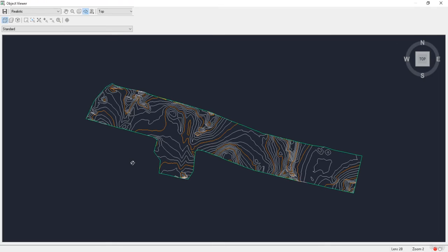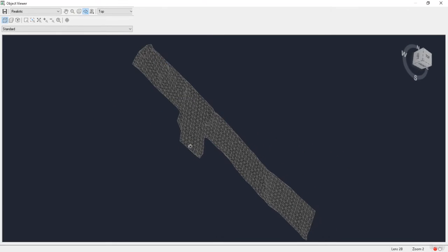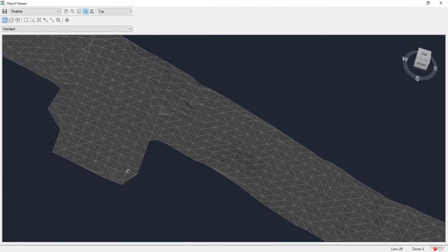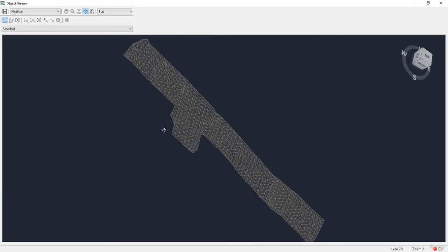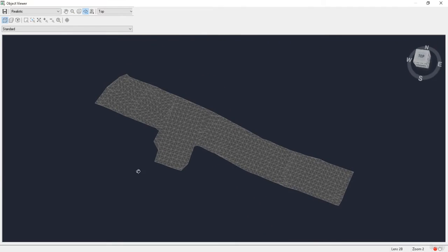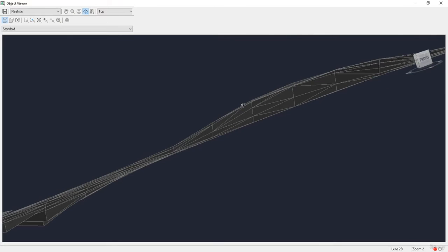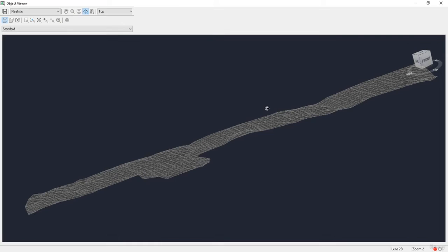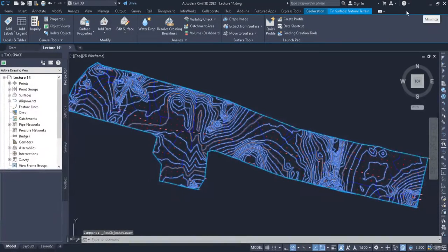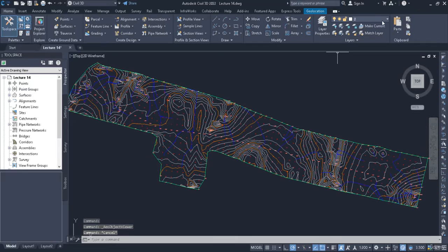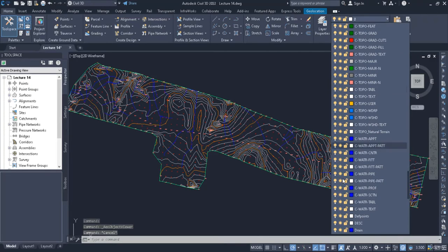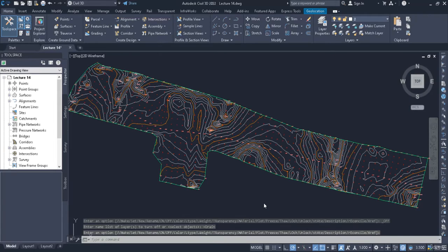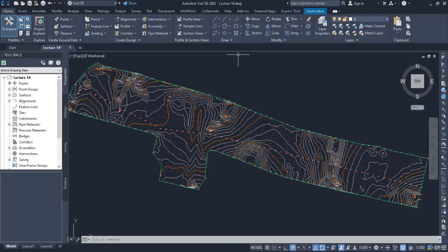We can go to the object viewer. You can see the slope areas. So this is the point where the water is going. See, if we land on these points, it will definitely go to the areas which are at the lower elevation. Let's turn off the drain layer from this point, so that if we want it in future, we don't have to make it again and again.